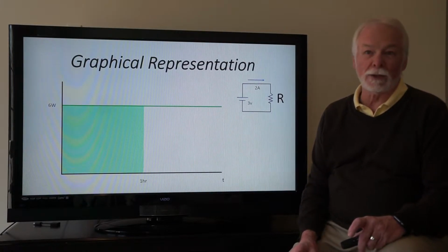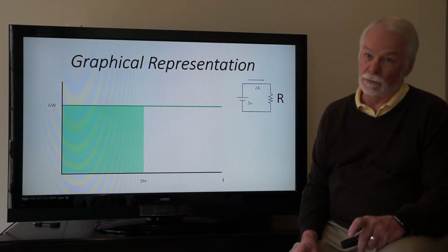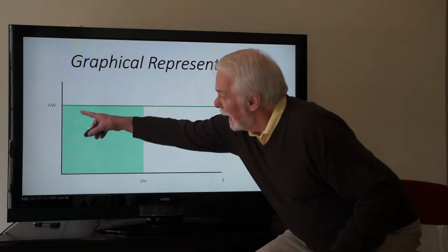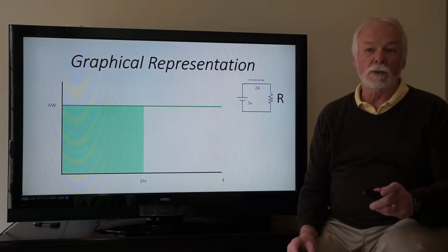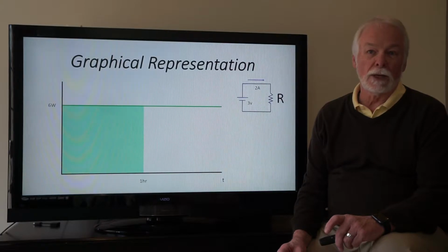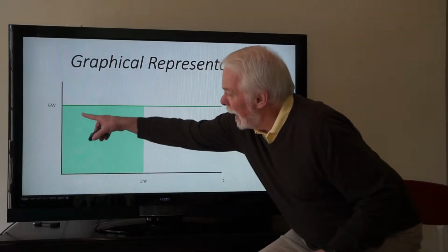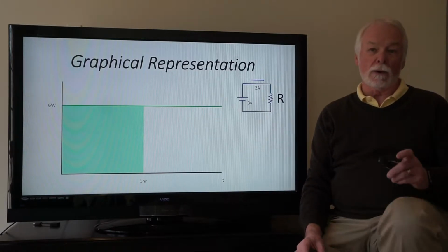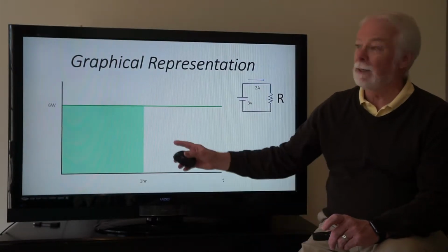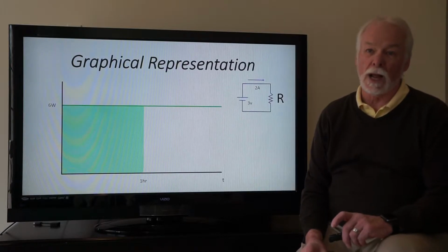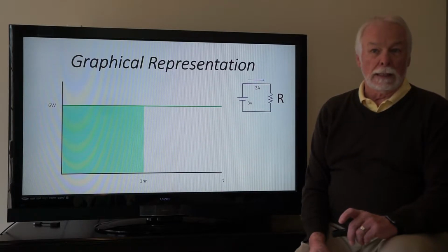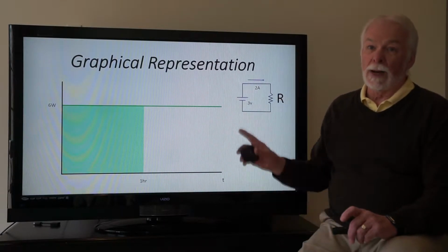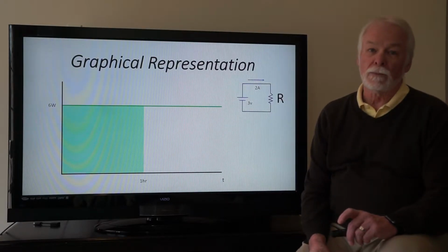It's very similar to measuring the rectangular throw rug in your living room that, let's say, is 8 feet by 10 feet. So 8 by 10 gives you 80 square feet. But in our case, one side is 6 watts, the other side is 1 hour. So the product, represented by this shaded area under the power line and bounded by the 1 hour mark, is the amount of energy consumed by this circuit in that time period. In this case, 6 watt hours.